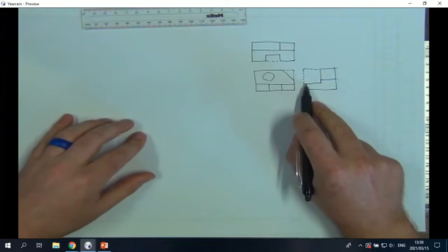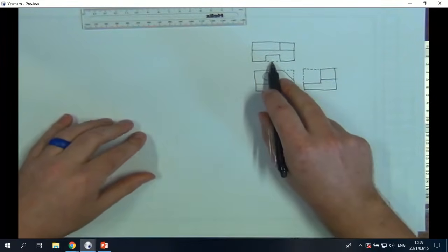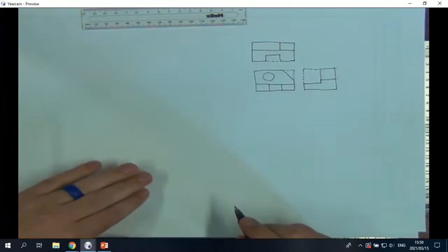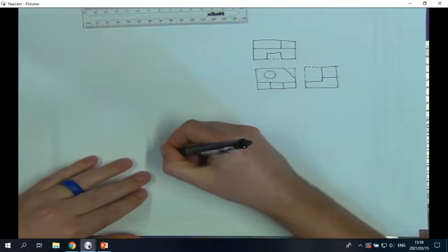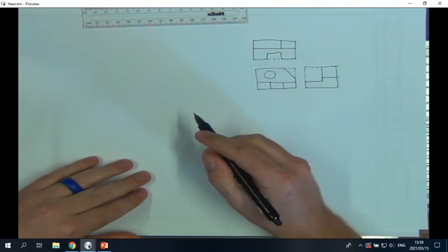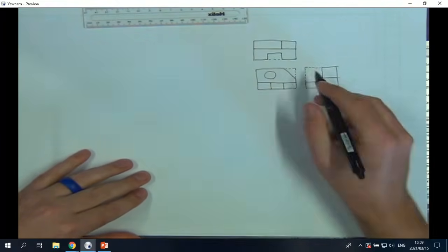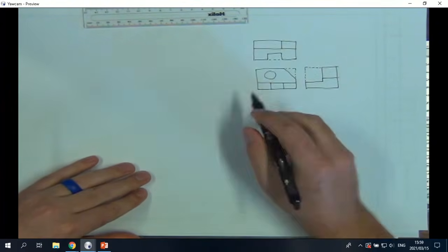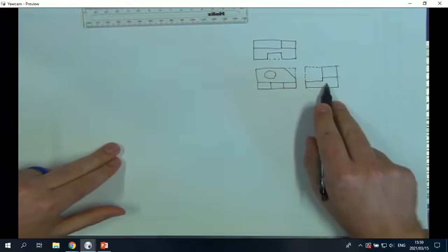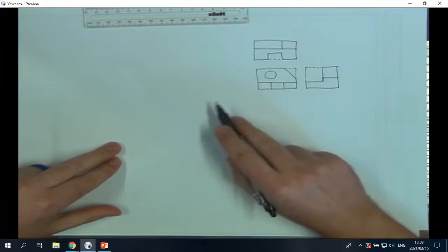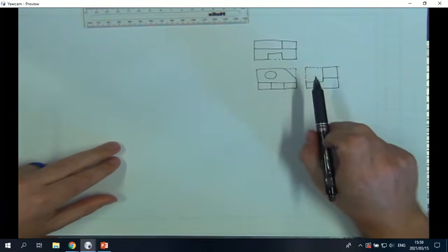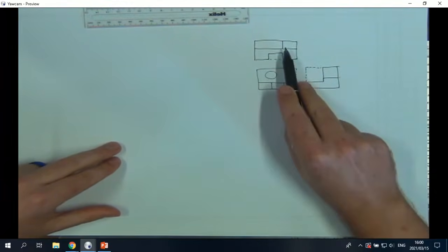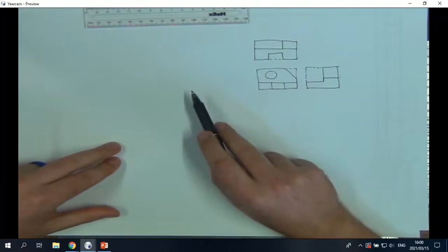These dotted lines, I've just quickly closed the drawing views so that I can make them into little boxes and draw the boxes. So for an isometric, this one I'm not going to bother about hidden details now. For the isometric, I want a view at the bottom left, one from the right hand side and the top. So usually with isometrics, we make sure that you give me what I give you. I must be able to see that view, and that view in the 3D picture.